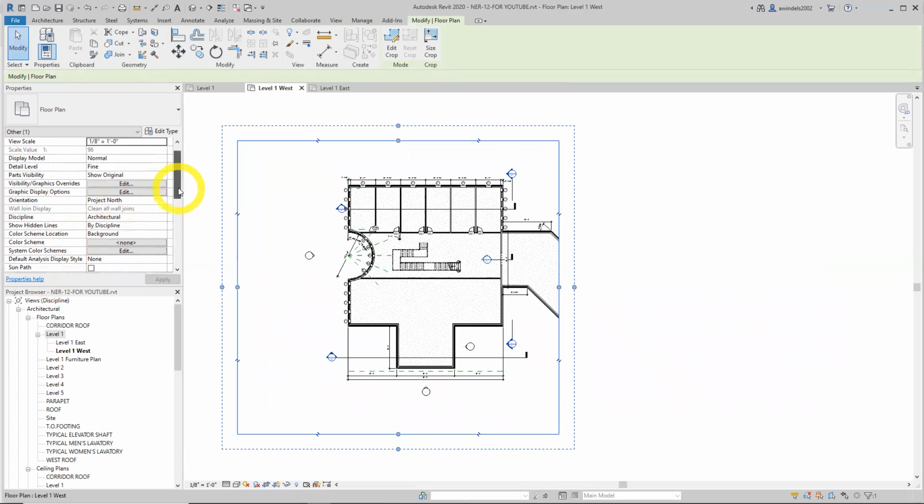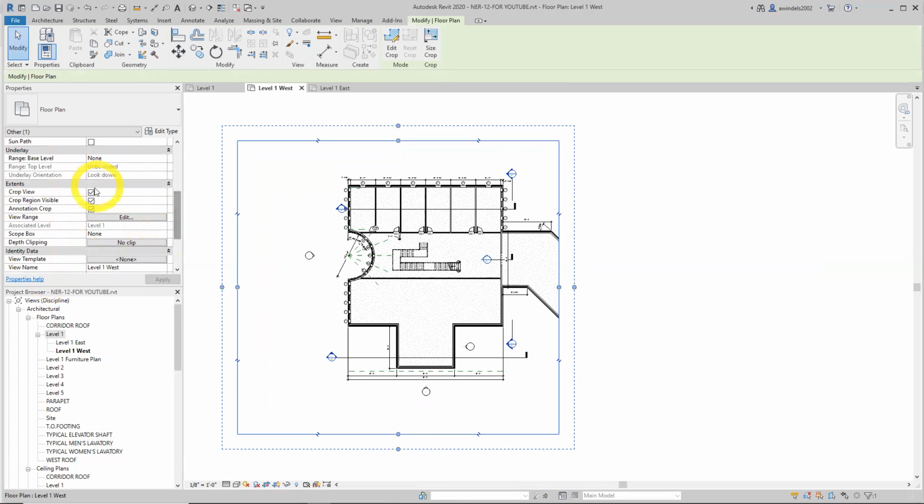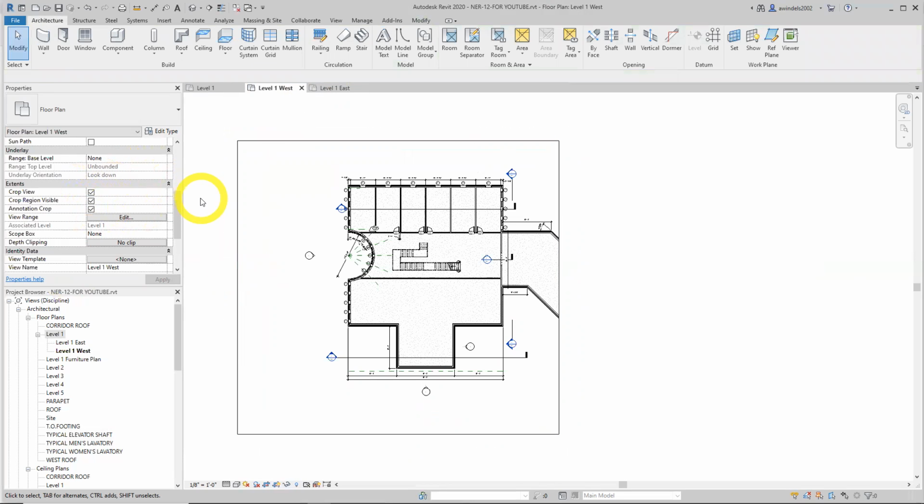And once again, they're saying at the bottom of page 623, you can turn things on here. So you might have got a file or people mess with a view. Check these settings. If you're not seeing anything selectable, go in here in your view, whatever view it might be, and turn these on. A few people had those off for whatever reason. Now going to page 624, we're going to talk about match lines.